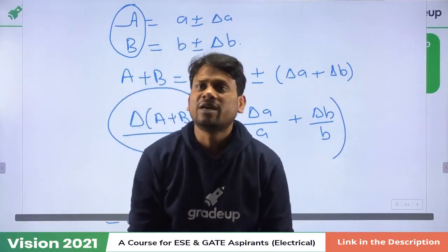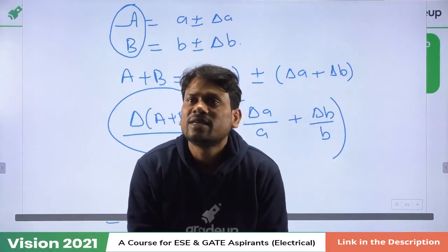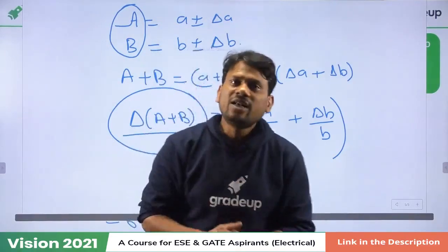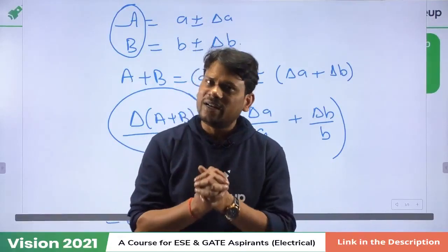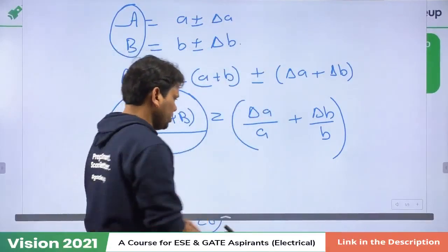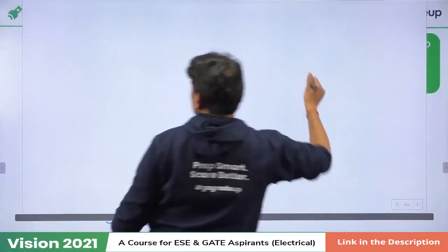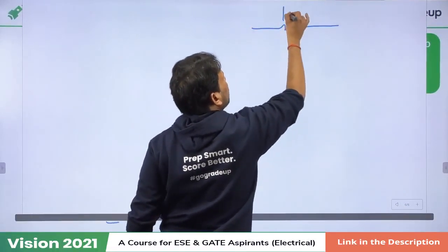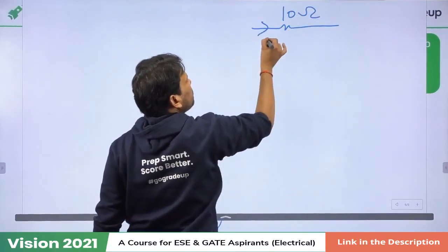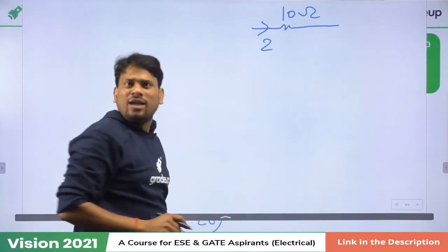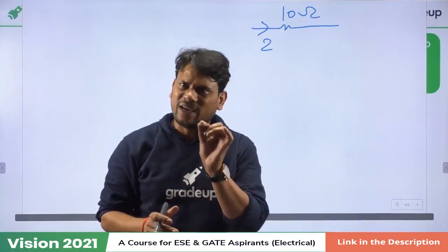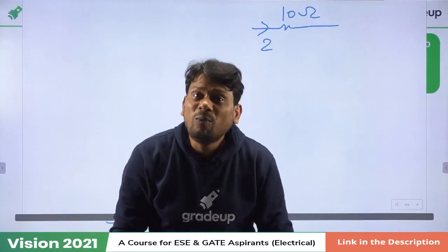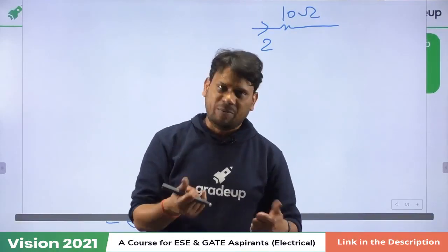Yeah, Venkatesh, I'm going to take one example from your side. Sir, some problem in taking error of values of power. Okay, definitely we are going to take another example related to power. Please mind it, related to power. Here, just try to understand, dear friend. Suppose we have one R of 10 ohm and I is flowing 2 ampere. And both these elements are error free. Please mind it, both elements are error free. Then obviously the error in the power will be 0.